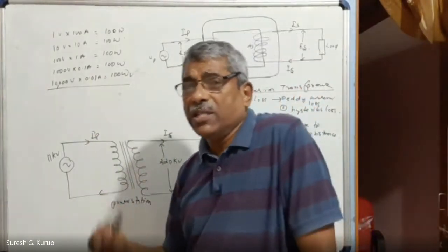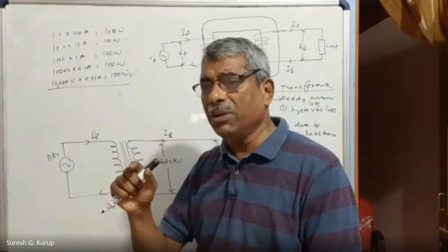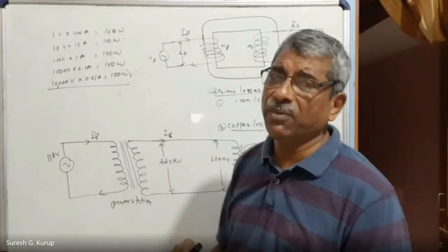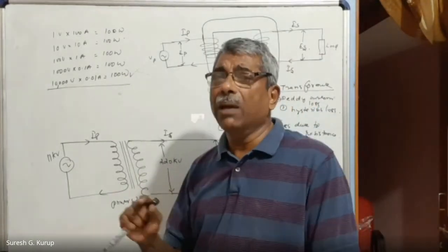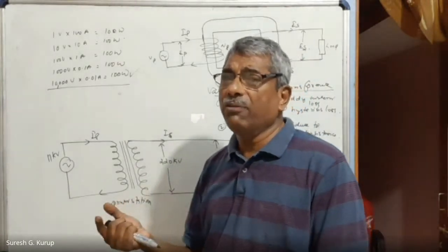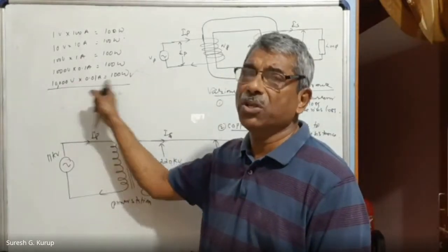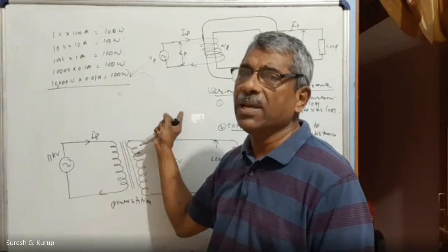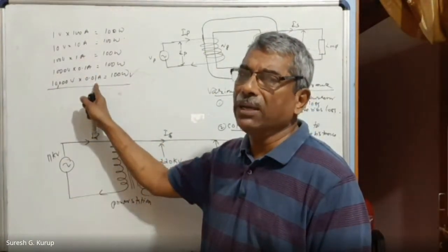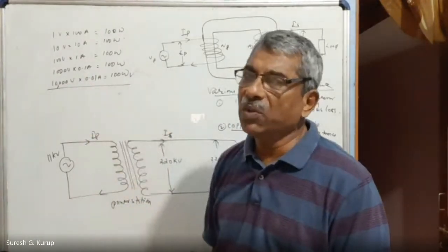Current value very, very less means the transmission wires can be very thin. That is also a question most of the time. Transmission wires of higher power lines are very, very thin. So does it make a lot of loss? No, because transmission lines coming from power stations to domestic places carry very, very less current. Transmission of current with a high voltage and less current is the only profitable way. Otherwise, it is a great loss.